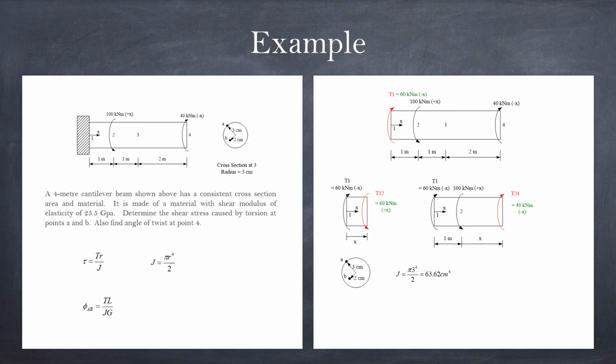The area itself, simple enough, right? Because we have the expression, we just use it and calculate the polar area moment of inertia. Notice one thing though: although we have 2 points to contend with, one at a radius of 3 and one at a radius of 2 centimeters, the J, the area moment of inertia, similar to I, is still calculated from the total area, not dividing the area before your calculation. Okay, the area moment of inertia in mechanics tends to be the total area.